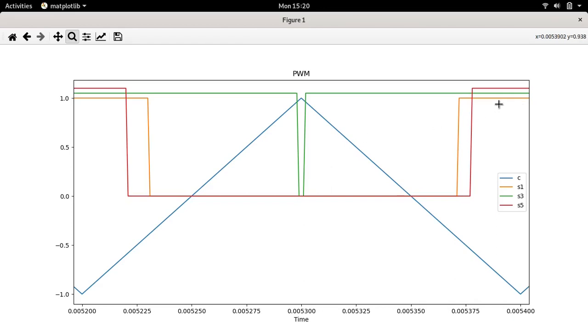Now, you could then bring both on times together as one continuous on time. So this on time here at the end of the cycle can be brought and joined somewhere here, right? You would still get the same on time. You would still get the same average output voltage. That does not change because remember, the average is merely the on time of the upper device multiplied by VDC. Because remember, we are taking the average voltage.